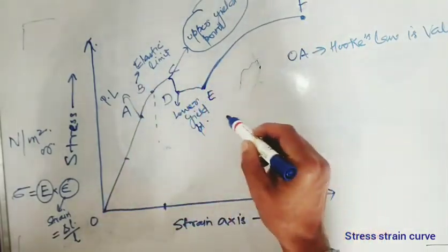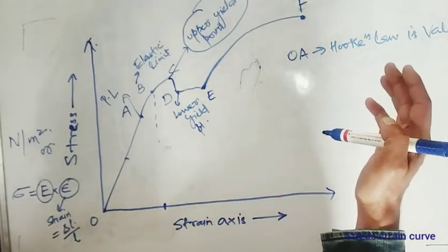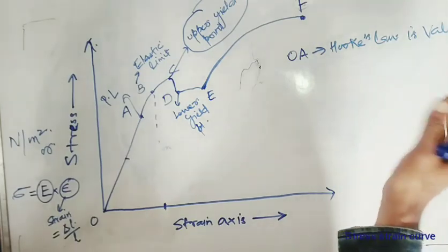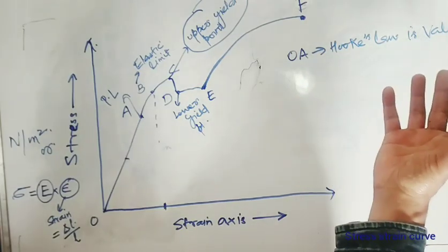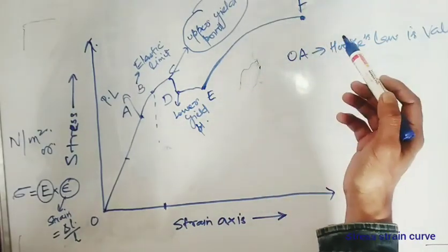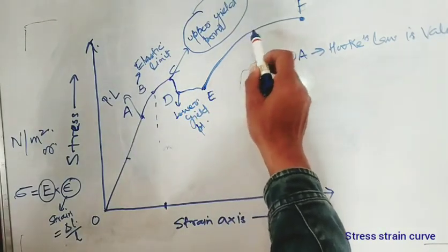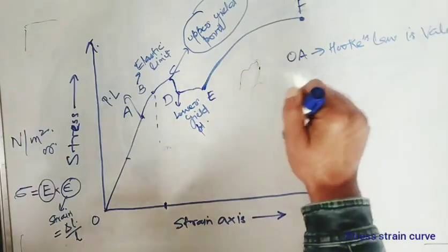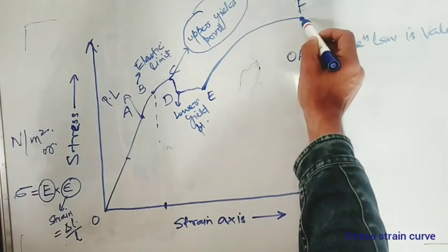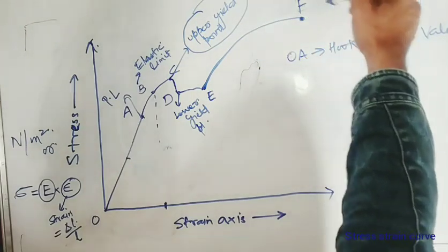If practically, for example, in an earthquake, when there is the yielding of steel bars, for example, in under reinforced sections, this yielding of the steel bars occurs first before the crushing of the concrete takes place. So if you want to visualize, over there will be yielding, and then again there will be strain hardening if there is more stress due to those earthquake loads, and after that your specimen will be having more strength. And at that stage, that will be called as ultimate stress point.